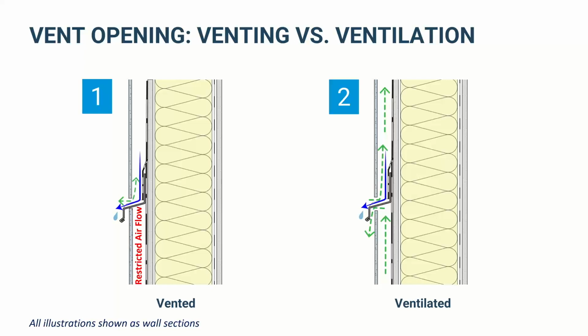And what that means is there is an opening, right? But you could imagine, you see that flashing is down tight against that cladding there below. So you can imagine this being repeated over and over again. So we have actually a way for water to vent or air to vent into this cavity, but we wouldn't call it ventilated because we don't actually have an opening at the top and bottom. This can actually severely restrict the amount of drying that can occur.